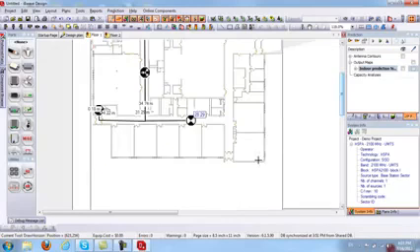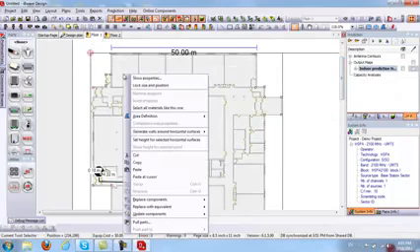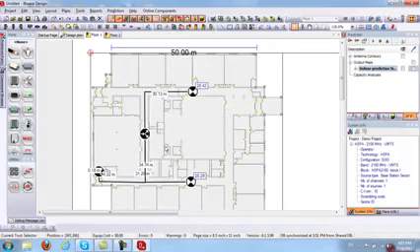And it is easy. You just cover your floor plan with your horizontal surface, and as you see, it snaps at all the corners. Very easy. So finishing this horizontal surface here, once I am done, I can click on it, right click, and select set as prediction area. So once I do that, now if I run predictions, they will run indoor only.